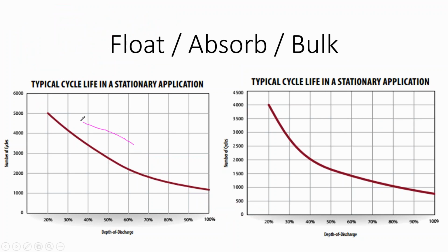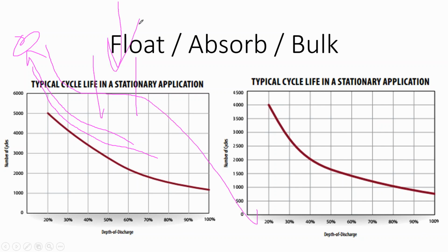And so when you charge a battery all the way up to full, it's actually going to go up into the above 50 volts. And as it's discharging, the voltage is going to drop, and it actually kind of makes a little bit of an asymptote that makes it hard to determine exactly how full a battery is by reading its voltage only.